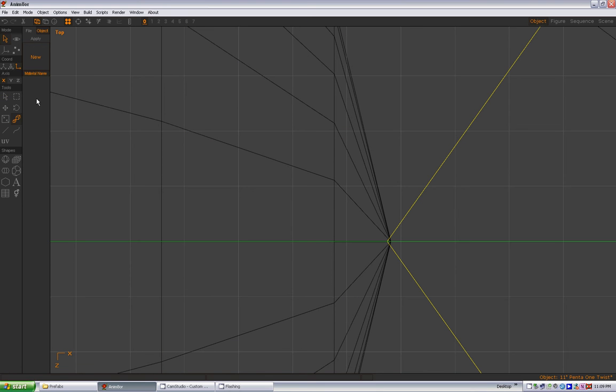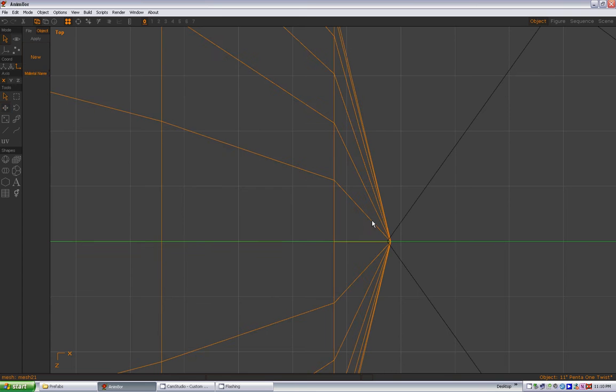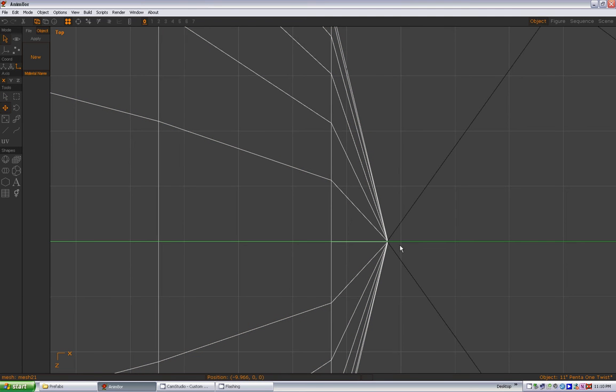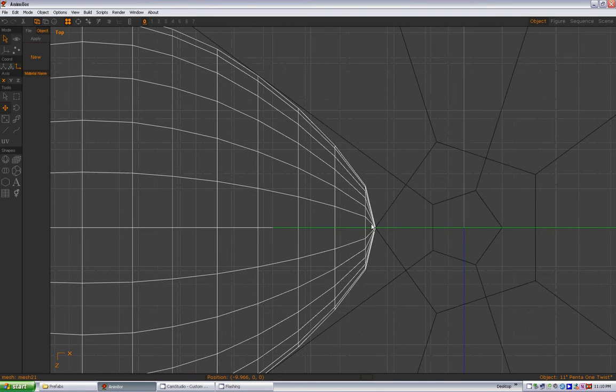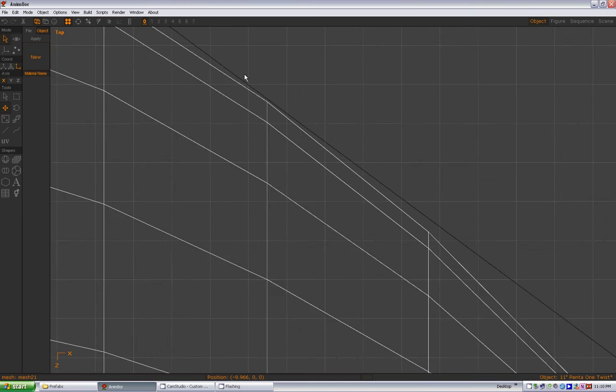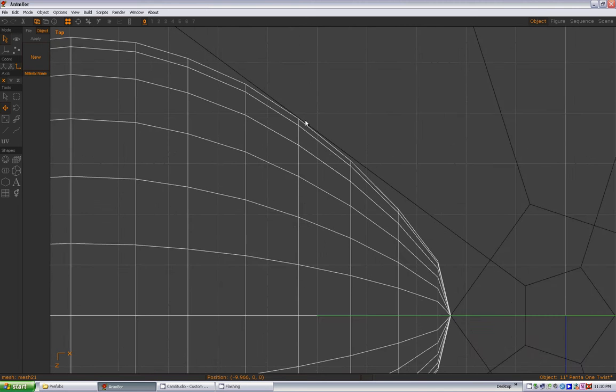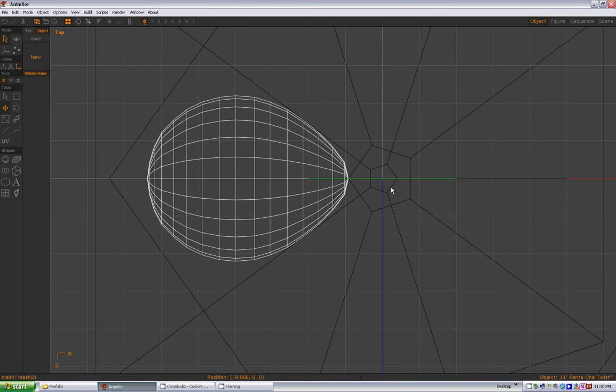So if you look over here and I hold down Control and Shift, you can see I can toggle back and forth. So no matter what tool I'm in, like if I'm in the Move tool, if I hold that, now I'm in the Selection tool. I'm now selecting. I let go of it, it defaults back to whatever the original tool was that I was on. So what I can do is use the Move tool, Control Shift to select this, and I'm going to arrow out until I get these two corners as close together as I can get them. So I'm going to wheel out now, and you can see my spacing's good here. It's pretty close. To the human eye, you're not going to see that.